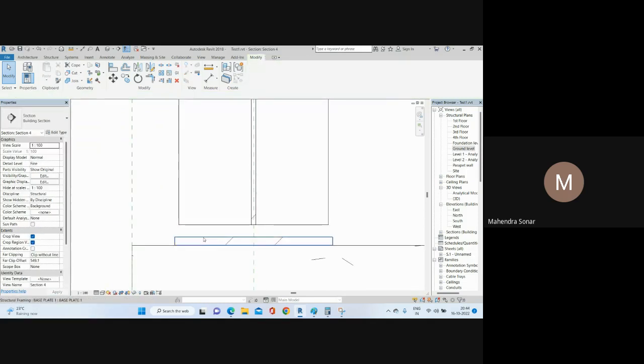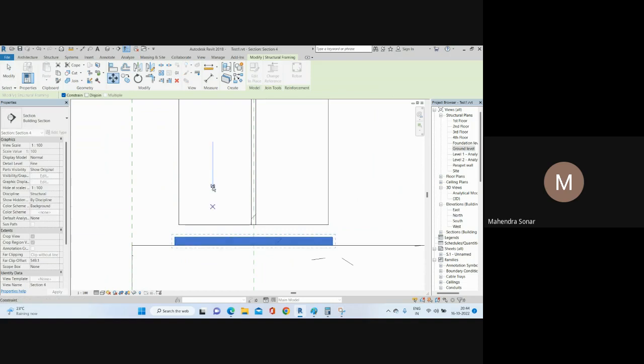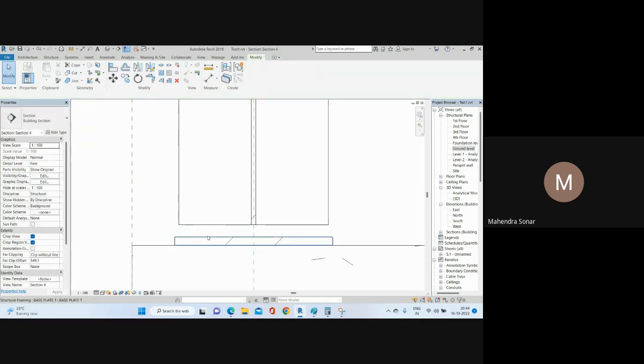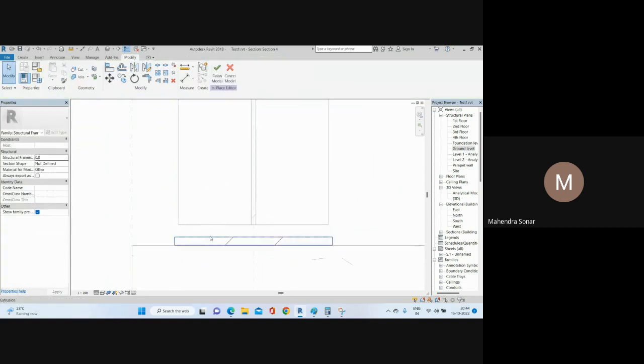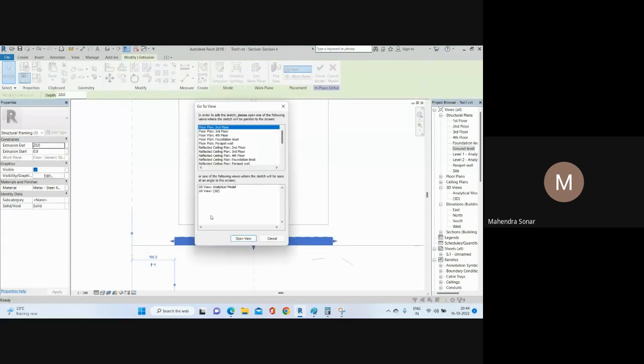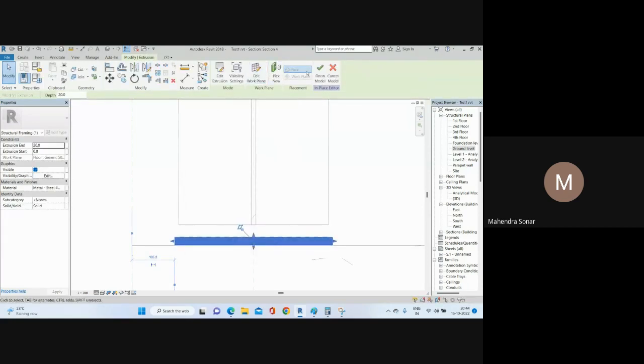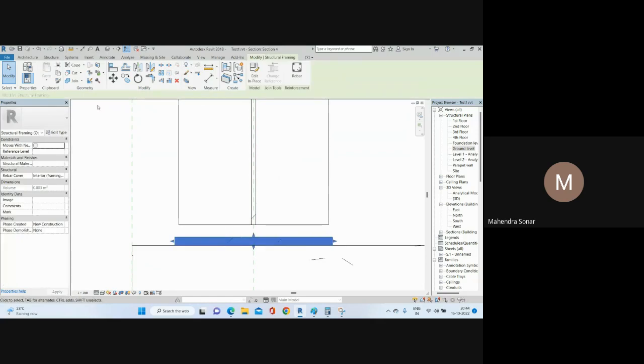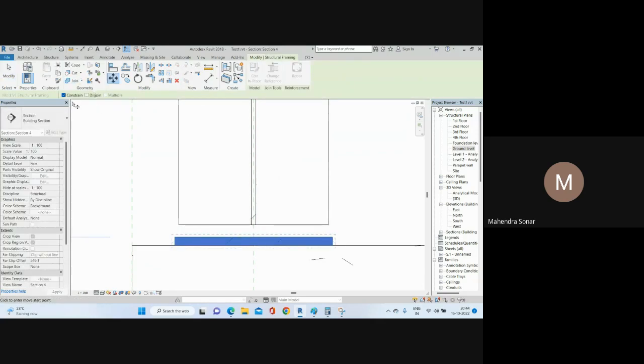Then after that you need to select this base plate and just move by 10 mm. Okay, so select and go to the edit in place and select this one and just move, sorry, not 10 mm, it's 20 mm, no 30 mm, because our grout is 30 mm, right. Okay, and then edit in extrusion. Okay, what happened, okay, just select and give the move command, right, and just remove this constraint. Okay, because your ortho is locked here. Okay, and this select on disjoin.